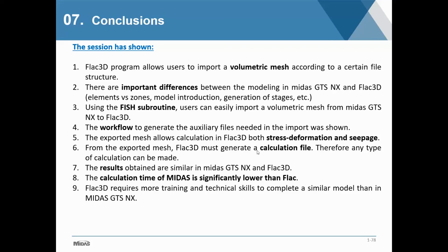In Flac, we also pointed out that we must also generate a calculation file, and not just the import file. Once the mesh is imported separately, you have to create a calculation file. However, that also means that any kind of analysis can be made in Flac because you code it yourself. We saw that the results match between Midas GTS NX and Flac3D for these examples.